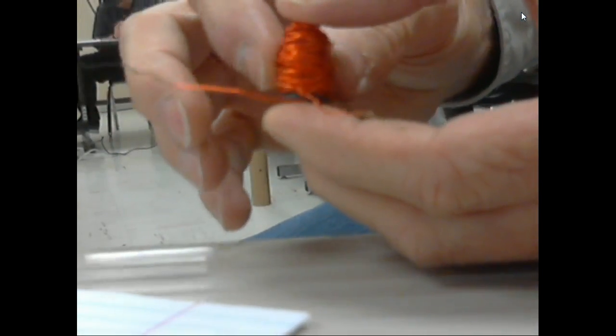This is called magnetic wire because for the magnetic fields to combine, you can't have hardly any insulation on the wire at all. Which means we've got to be real careful with this because this stuff will scratch off. So a lot of times this will all be encapsulated inside a big nice chunk of plastic, so you can't scratch off the covers on the wire and create shorts. But this is just homemade, so this is magnetic wire. I'll pass this around. The insulation is really, really thin. In fact, to strip this, you just get a blade and scratch it off.